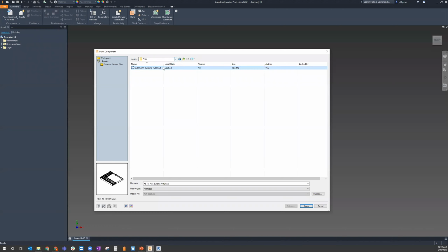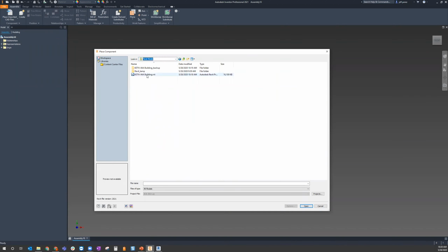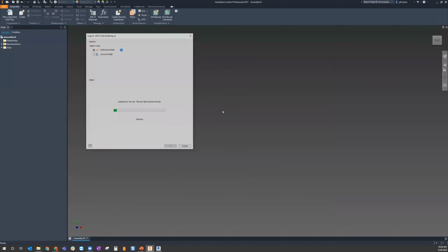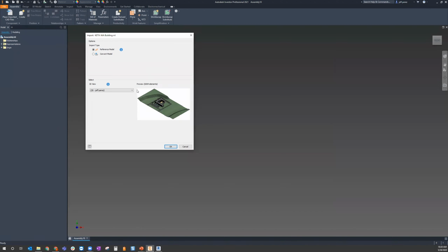Okay. Now that change I just did for that 3D view isn't a part of this BIM 360 project, so I'll go back to my native Revit location, and I'm just going to click Open. Now what's going to happen here is Inventor is going to use AnyCAD functionality, and it's going to allow you to pick and specify the exact 3D view you want to insert into your project. And in this case, I did create this view, 3D ceiling space.